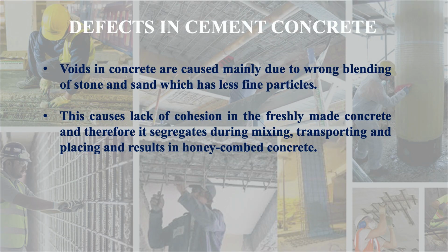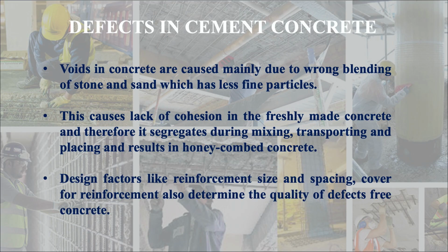This causes lack of cohesion in the freshly made concrete, and therefore it segregates during mixing, transporting and placing, and finally results in honeycombed concrete. That is the reason for honeycombed concrete. Design factors like reinforcement size and spacing, and cover for reinforcement also determine the quality of defect-free concrete.